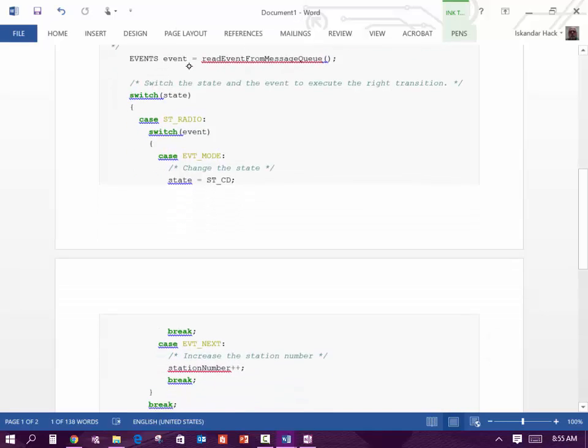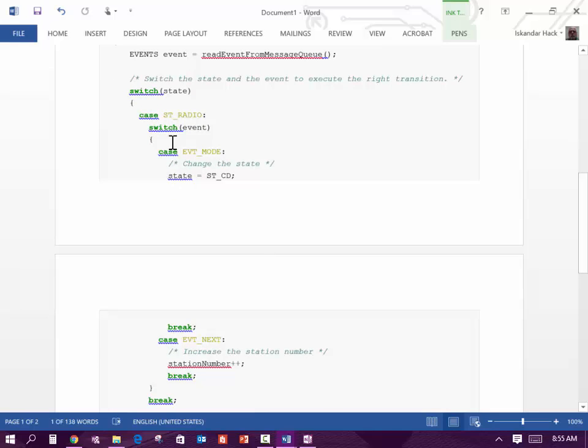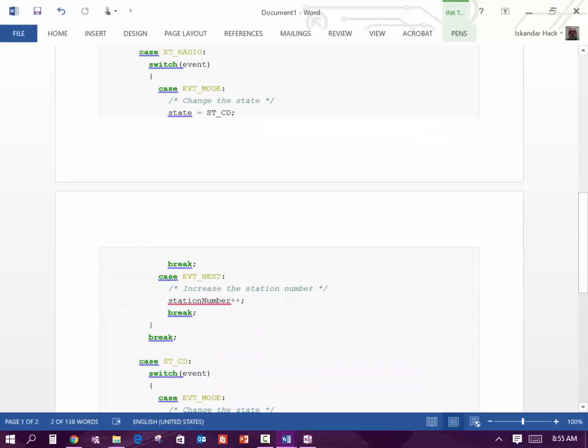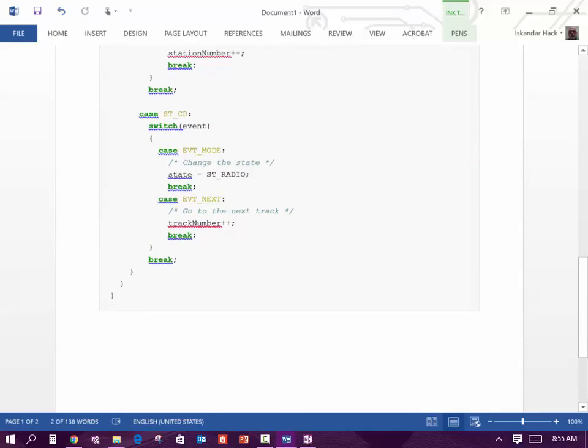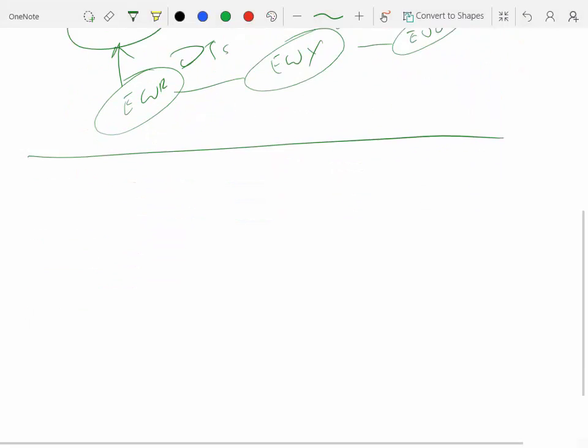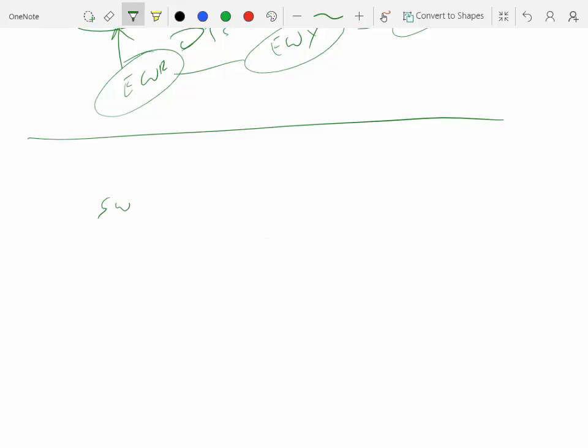Now, there is a structure in C called the switch command. It's a switch case statement right there. And let me just go through here. When we look at the switch state, there's switch, and then we put a variable name, and I'm just going to put state in here, because state is probably what we're going to call it.